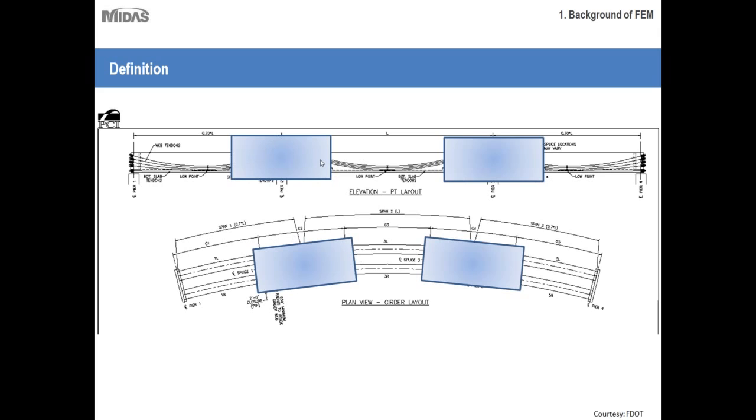In these zones you have to apply the lid slab on top to cover the U-girder opening and provide enough stiffness to the section to avoid any kind of torsion in the segment and give it its stability. Because after this stage we will be doing the post-tensioning and applying the deck slab on top of it.